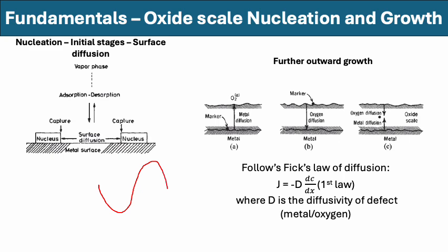What that driving force implies is that if you see the metal phase or the alloy phase, and the oxide phase has the lower energy, there is an energy difference. If you see these two lines that I am drawing here, this is the driving force for oxide formation. This is the chemical energy driving force, expressed in terms of the volumetric free energy difference between metal and oxide.